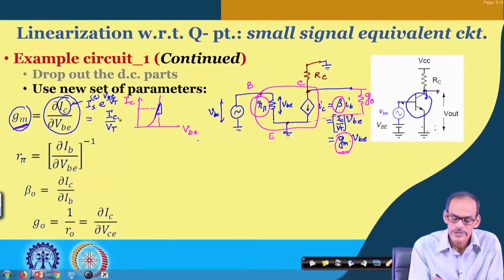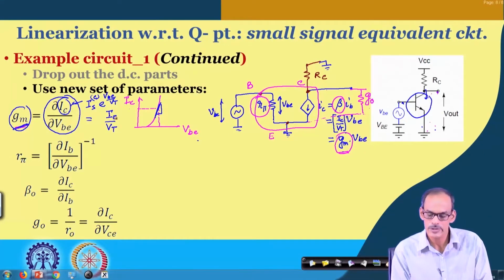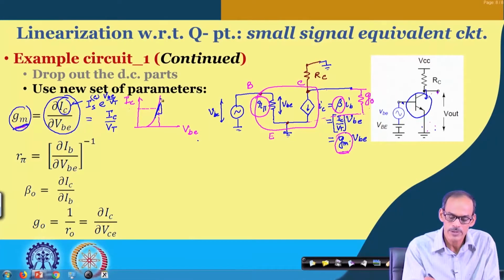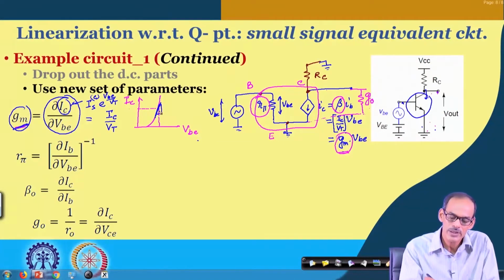Okay. And this IC, of course, is the instantaneous IC, which is the slope, and it depends on the instantaneous value. But if we restrict our discussion to a small range, then we can say that this IC can be well approximated by capital IC, namely whatever current we have here at the DC operating point.